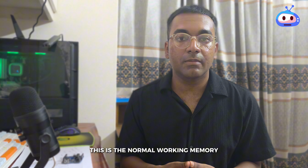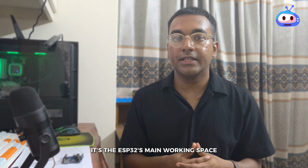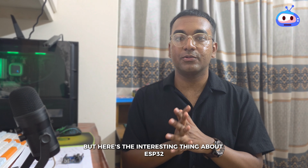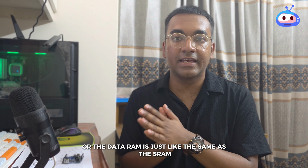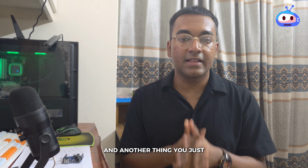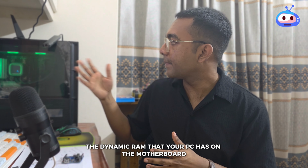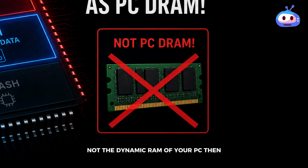This is the normal working memory for all the variables and all your runtime data. It's the ESP32's main working space. But here's the interesting thing about the ESP32: the DRAM, or data RAM, is the same as the SRAM, or static RAM. They just call it DRAM to distinguish it from the IRAM of this board. And don't mix it up with the dynamic RAM that your PC has on the motherboard. The DRAM on the ESP32 is the data RAM, not the dynamic RAM of your PC.